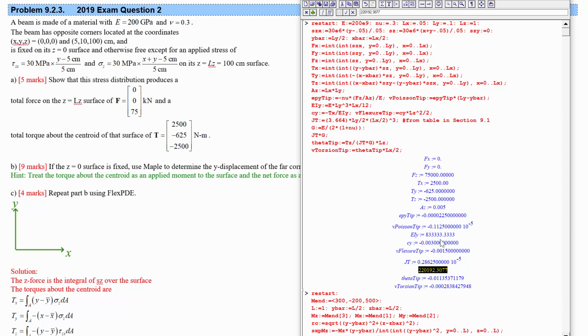So it's easier to get a certain amount of twist angle, but the twist angle that we get doesn't actually lead to too much displacement because that gets multiplied by Lx over 2, whereas the bending one got multiplied by a different factor. This was sort of like an Lz along the way, and then an Lx over 2, and the bending one just got multiplied by an Lz squared over 2.